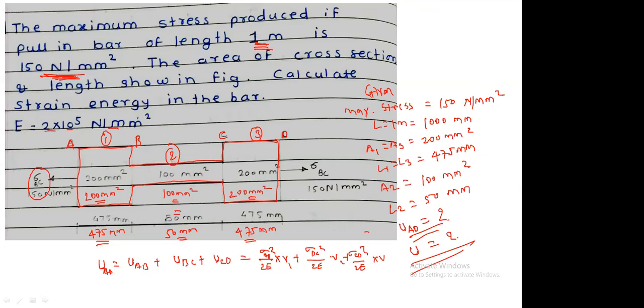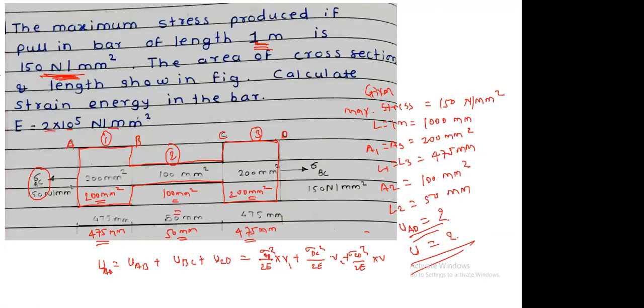Here we can apply one concept. What is that? Stress is maximum where area is minimum. Now please tell me, in the given figure, which area is minimum, whether section 1, section 2 or section 3?